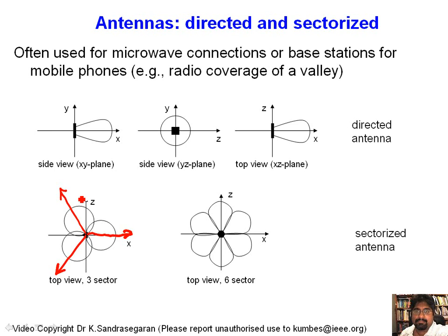So gain. Okay, you can get a much higher gain using directed antennas. Okay, so because you get a much higher gain using directed antenna, if you look at the 2 antennas that you have on the diagram, you see that one is a directed antenna and the other one is an omnidirectional. And if you look at the gains, there's a big difference.